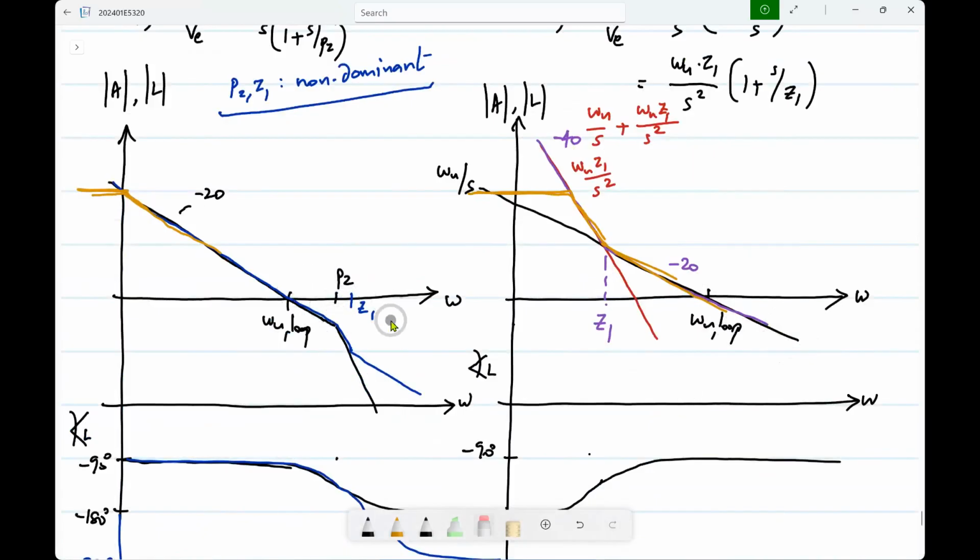So now if you look at these op-amps also and ask what is the highest unity gain frequency op-amp I can realize, using either the Miller compensated topology or the feedforward topology, which one will it be? The thing is that these parasitic poles are roughly like Gm by C. They are related to the inherent speed limit of the process.